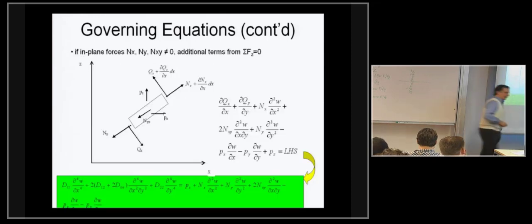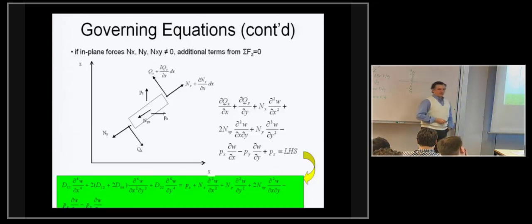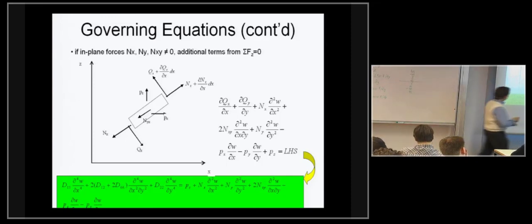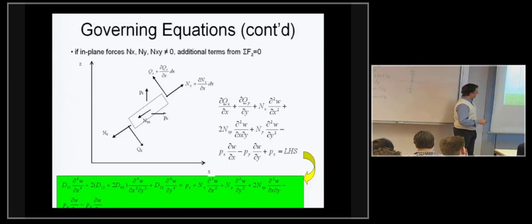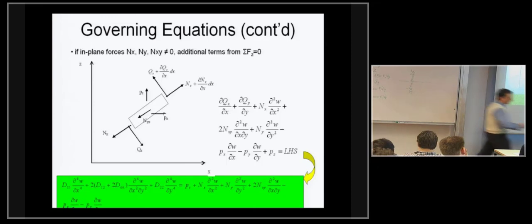And there's a variation of those equations if you're trying to do a buckling analysis, you have to include some kind of first order effects. And briefly mentioned here is how you would do the force equilibrium in the Z direction. And the book has the complete derivation in much more detail. Basically, if you look at this equation at the bottom here, I have the D matrix with the fourth derivatives of W, and those are the same,